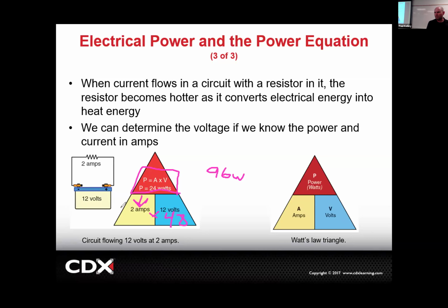So even golf carts. Have you guys seen electric golf carts? Electric golf carts mostly are going to be like 36 volts or 48 volts. So they took the 12-volt batteries or 6-volt batteries, and they wire them up in series to get a good voltage so that they can actually get pretty decent power to move that golf cart. Cool, so pretty fun. It's a good calculation to know.